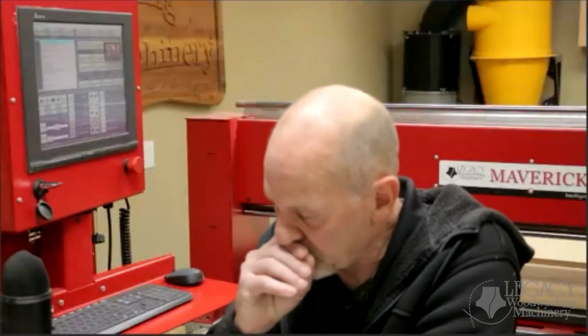Anytime you run the program, the M6 is going to grab the cutter and take it over the Smart Tool pad. It's going to touch off, and it's going to set the Z to that value. So if it's lower than the table by 1/8 of an inch, it would set it to a minus 0.125. If it's higher than the table, it would set it for a positive, whatever the distance is. Okay, it just records that, and every time it touches, that's what it puts in the Z axis, and so